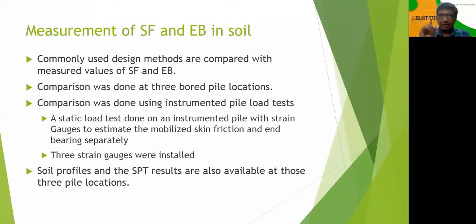At these 3 locations they have done borehole testing, the SPT within a reasonable depth. So what we do is compare the measurements with the estimation methods, for both skin friction and end bearing. All these piles are within the soil, not supported on the bedrock, so we can determine the skin friction in soils and end bearing in soils, the mobilized ones.